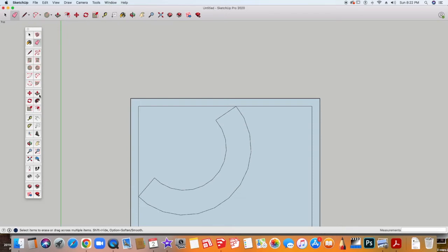And I might even use the Offset tool here again to create another offset. And maybe this time I'm going to use the pencil tool and bring that edge to here. Click Escape to get out of the tools. What is important is to check and make sure that you've actually cut the surface. Here, I'm going to do the same thing. I think I'm going to draw a line here. And maybe I'll delete this line here around the edge, and maybe I'll use the Offset tool again.